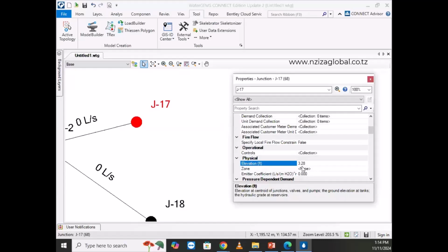To mean, it's different from EPANET. In EPANET, when you change the unit, you have to calculate also what you change into the unit. In WaterCAD, it calculates itself. When you put things in meters, it immediately calculates those things in meters. When you put it in feet, it immediately calculates those things in feet. Which is different from EPANET.